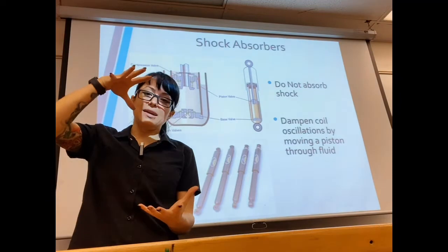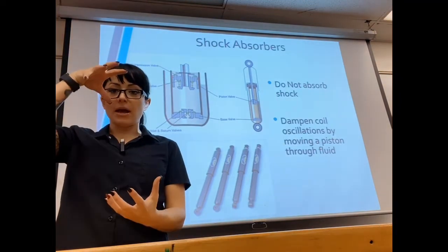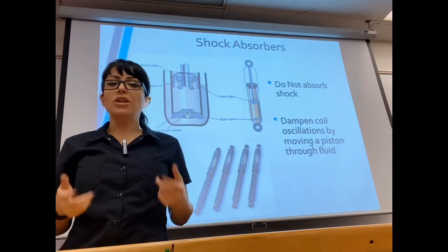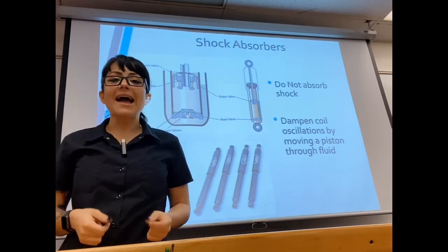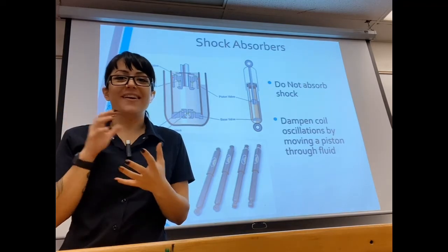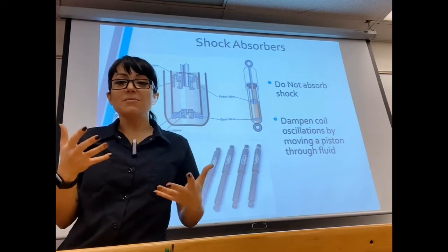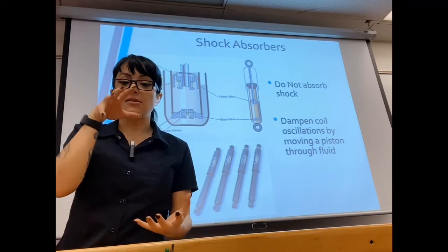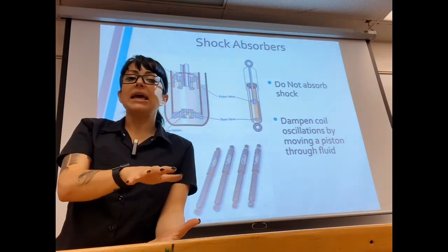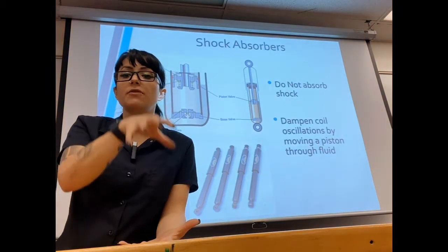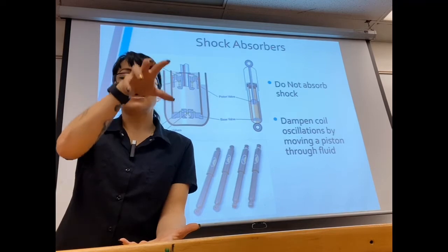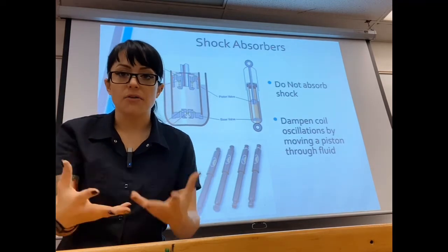When your spring goes through jounce and rebound, it doesn't just jounce and rebound and stop, right? When you think of a spring moving in action, you get that sound in your head, right? That boing, boing, boing. That sound comes from spring oscillations. So when I compress a spring and then release it, it is going to go through its motion of compression and rebound, and it's going to do it less and less until it's got all that energy out.